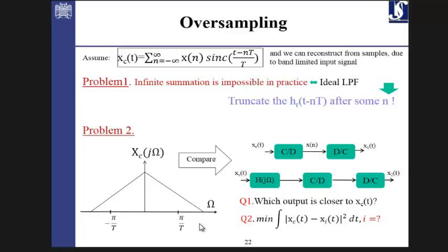You can investigate this, which is called the anti-aliasing filter. The anti-aliasing filter, before starting any process, is applied before even going inside the continuous to discrete conversion, the A to D conversion. And that implicitly means this anti-aliasing filter is actually applied to the continuous time domain signal, not the discrete time domain signal.